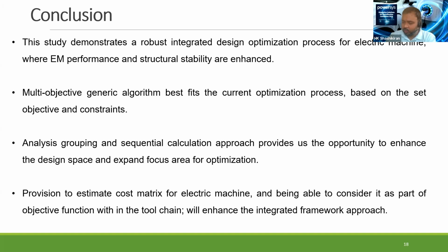So for the baseline, we did a complete 3D model and 2D model comparison. But as we are not considering the leakage fluxes and other things as optimization for the current design, we did not see a major difference in overall torque production. Of course, there were 1% or 2% increases and decreases in voltages and torque numbers.